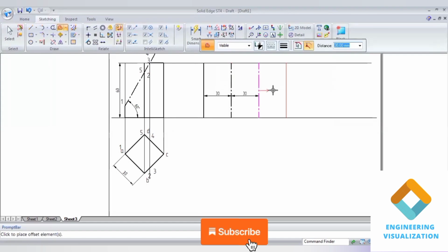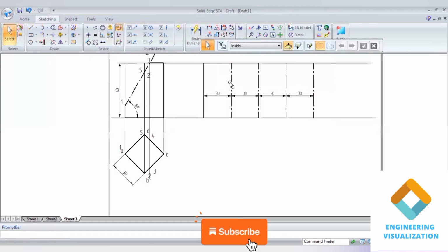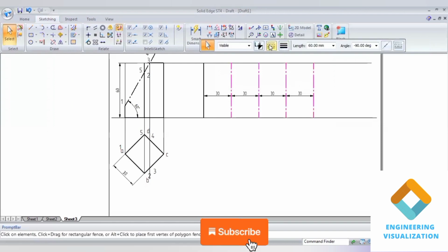Now here you can see the dimension, it is 30. Totally there are 4 faces in the square prism. So using the offset command, I will give the distance of 30, and then I will click 4 times. I will get the 4 faces here. I'll make all these lines continuous.